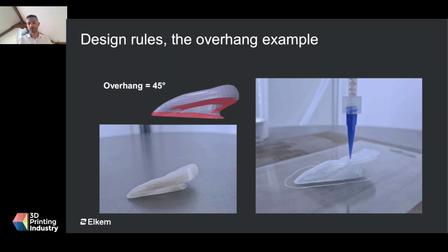of 3D printing. And now one of the main things that you have to take into account when you speak about extrusion process for 3D printing is the overhang. Here, you can see the example of an ear with a very tricky zone regarding the overhang that you can see on this slide in red. But if you combine the right rheology and the right curing of the product, you can print this kind of geometry even without support material. It's not impossible.